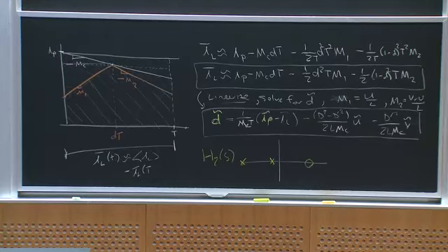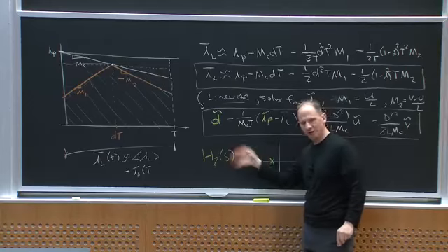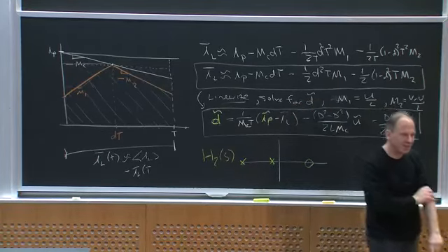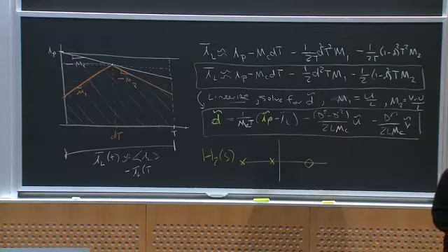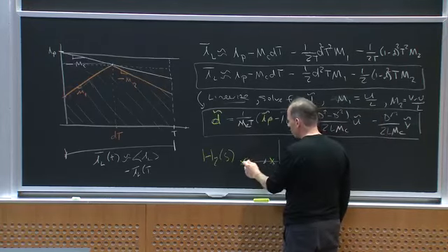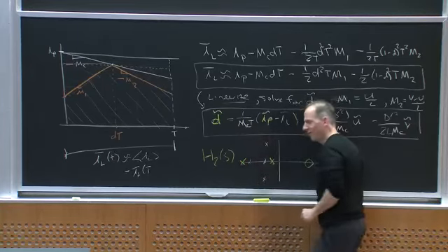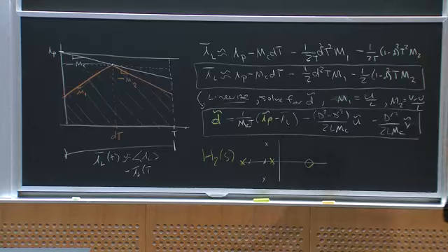And when I told you that I get a really low frequency pole and then a high frequency pole, both on the real axis, that's when MC is small. As I make MC bigger and bigger, these open loop poles move, and if I make MC too big, I get undamped poles again. So basically, the higher this value of MC, the closer the converter transfer functions in current mode control look like they do for duty ratio control or voltage mode control.